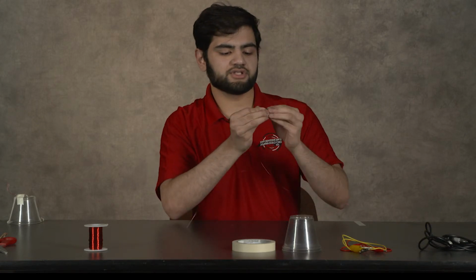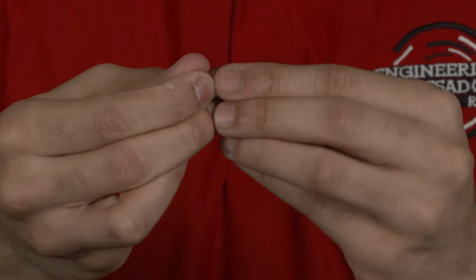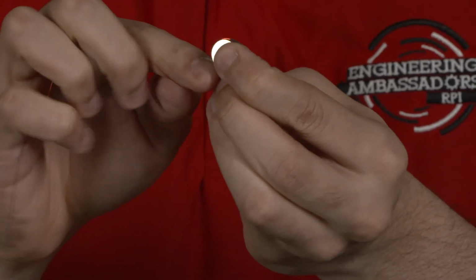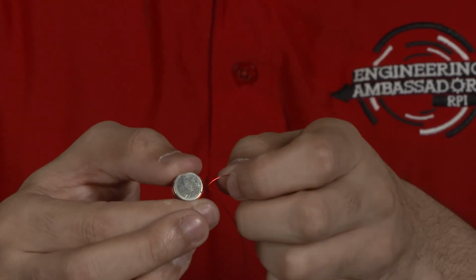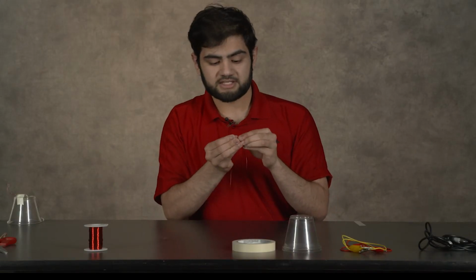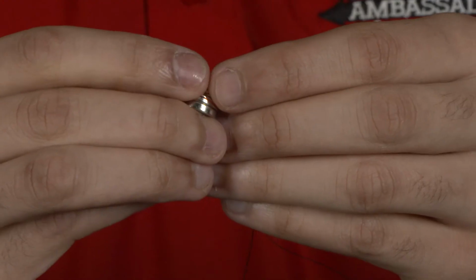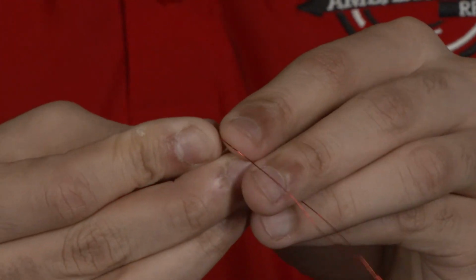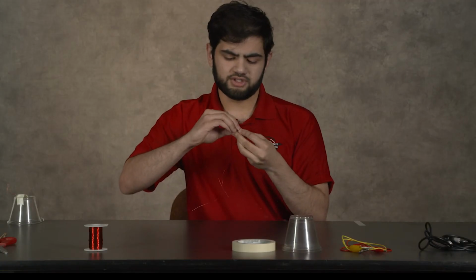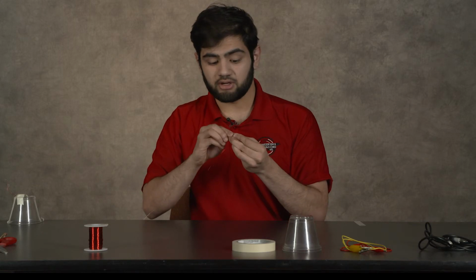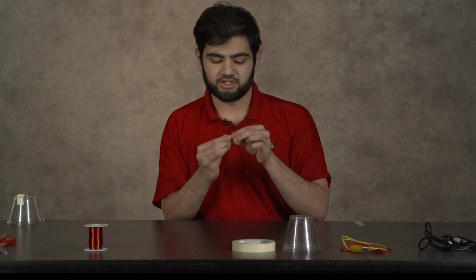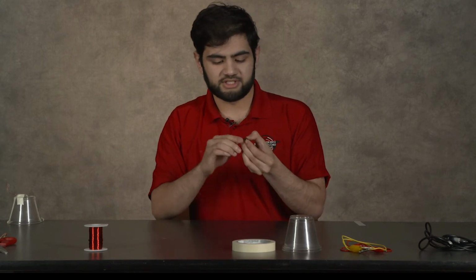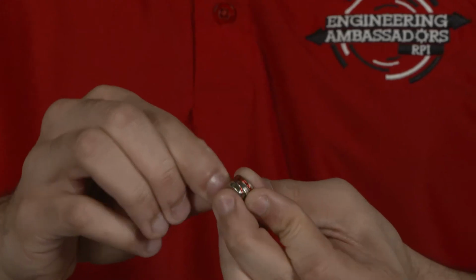The first loop is really hard to get on just because it really likes to move. Once you've got a couple on there, it becomes a bit easier. One of the rules of electricity and magnetism is that if you're trying to make a temporary magnet, the magnet's going to be stronger the more windings you have. So really try to get as many coils as you can fit in that small area, and you'll get louder speakers. If you find that once you've done this activity and you've plugged it all in, you're not hearing anything or it's really quiet, one of the issues might be you don't have a strong enough temporary magnet. So go back to this step and see if you can squeeze in some more windings into your design.